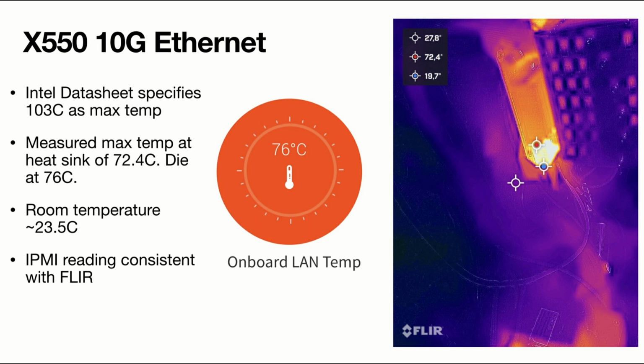The Ethernet links were up, but I was not running any benchmark and it already went up in these temperature ranges. I've also tried measuring temperatures under load, so using iPerf to generate traffic on the device. However, I could not observe a significant temperature difference. As on the 10G Ethernet, we are 12 degrees lower compared to the X570 chipset. Even if we assume that the air temperature inside the chassis will be higher, and we assume it's 10 degrees higher, we are still at 86 degrees.